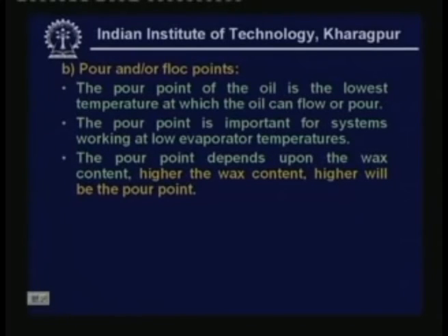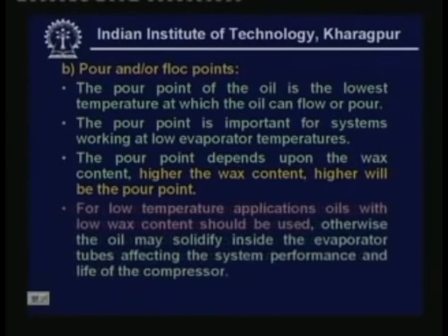Okay, and it is found that the pour point depends upon the wax content. That means higher the wax content, higher will be the pour point. And for low temperature applications, obviously we require oils with low wax content so that we can have low pour point.